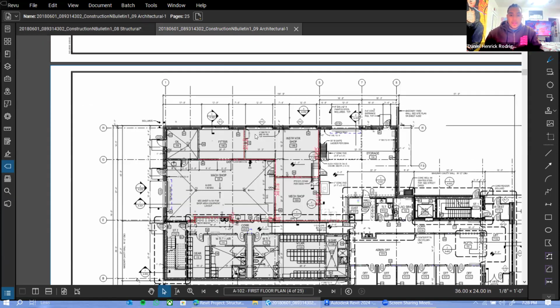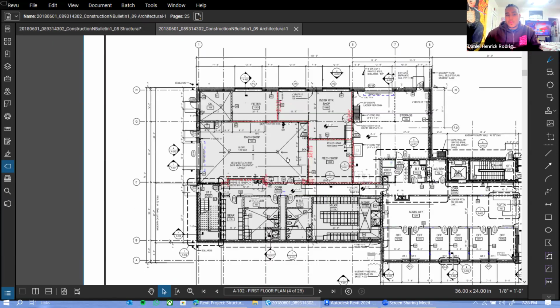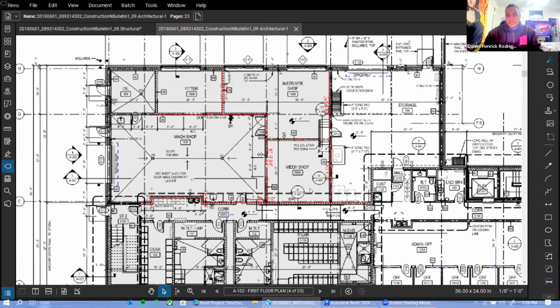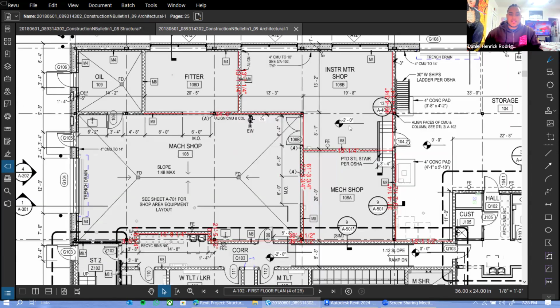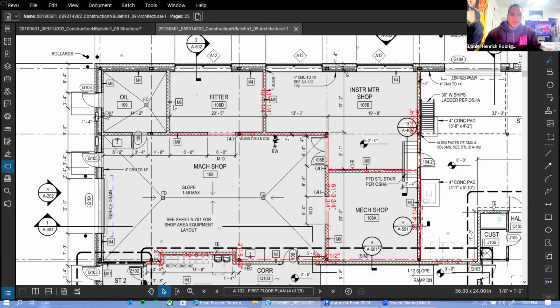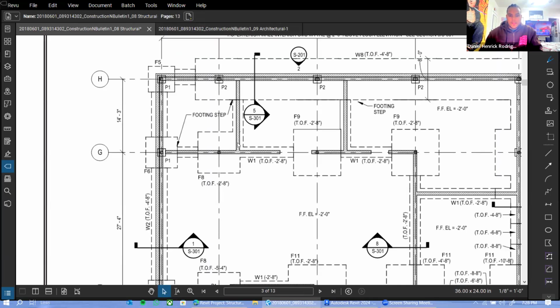But what I'm gonna mention to you guys is that all the walls of the first floor of the building are masonry, and they're actually the same walls that go below. So this M8, as you guys remember, is a masonry wall, 8-inch, and that's what's going to be these walls that go below the slab on grade. Okay, and then we have the EW3 on the outside.